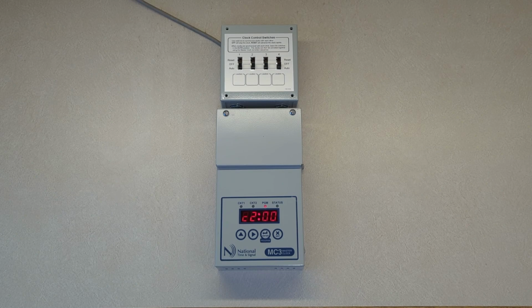Now you can choose the circuit type for circuit 2. Use the up arrow to set this to 0 because circuit 2 is not used for architectural clocks, even if you have multiple clocks hooked up to a 4-switch module. If you have a 4-switch module, all the clocks are controlled together through circuit 1. The clocks can be individually controlled using the manual switches on the 4-switch. With the circuit type for circuit 2 set to 0, press the Enter button.